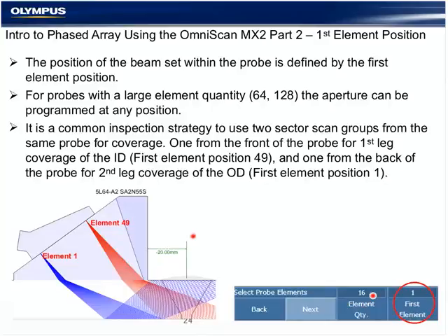In this case, this probe has a 0.6 millimeter pitch. So if I use 16 of them times 0.6 millimeters, that is going to give me a probe aperture just short of 10 millimeters. The two parameters I'm seeing here are simulating a 10 millimeter by 7 millimeter conventional beam. And we can manipulate it with a beam tool plotter like you see here, or directly in the instrument.